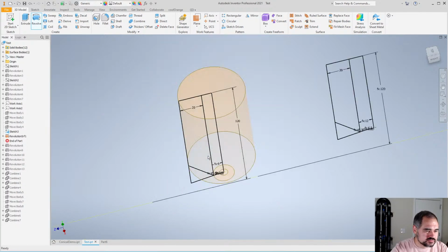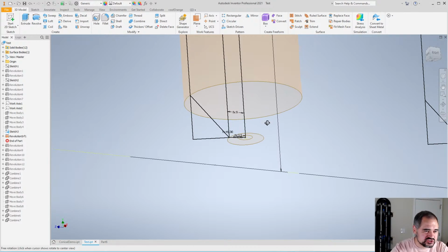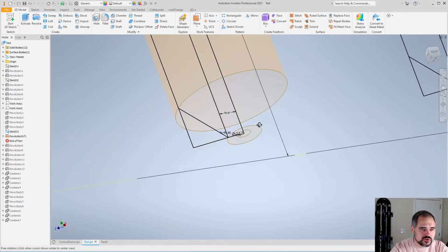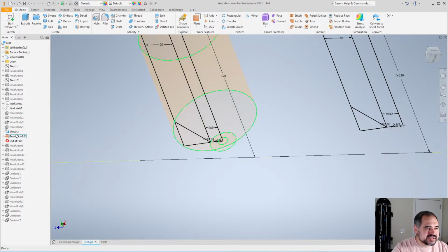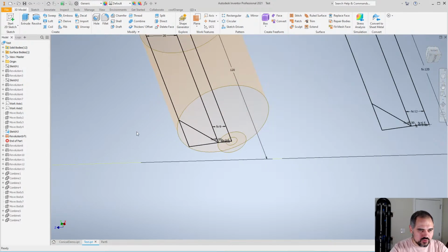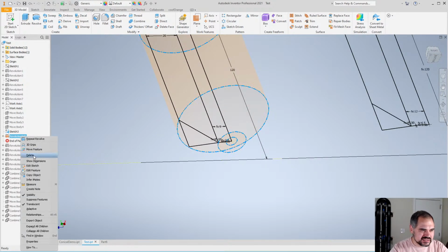The problem comes if I change anything. When you have these surfaces and you're using them to cut a solid, the surface has to cut the solid completely. If it doesn't, everything fails. It would still fail even if it were modeled as a solid, but the way that it fails is much easier.